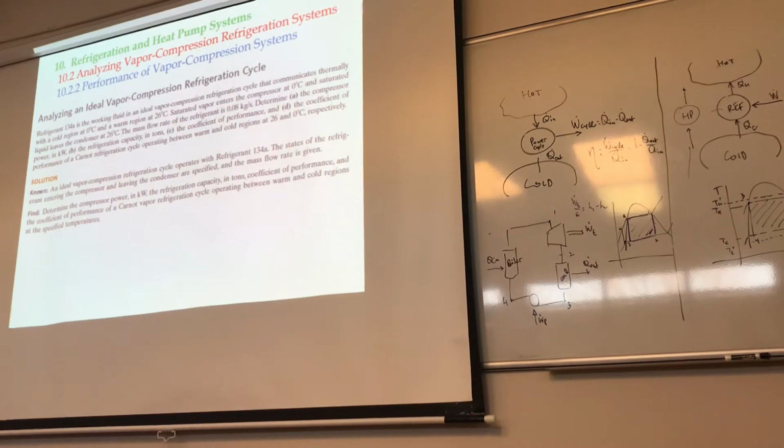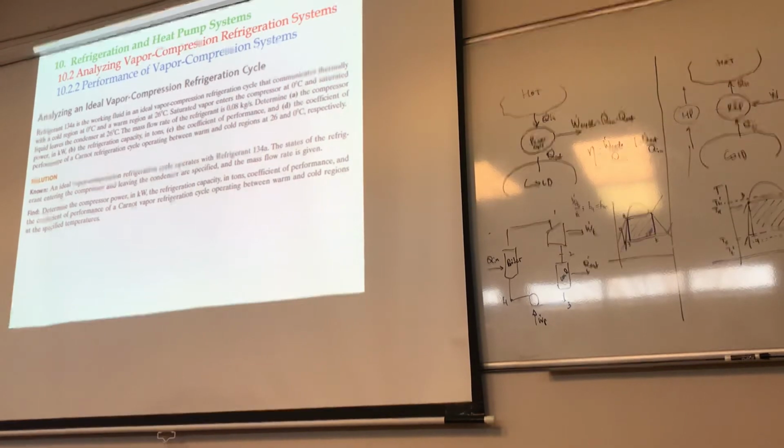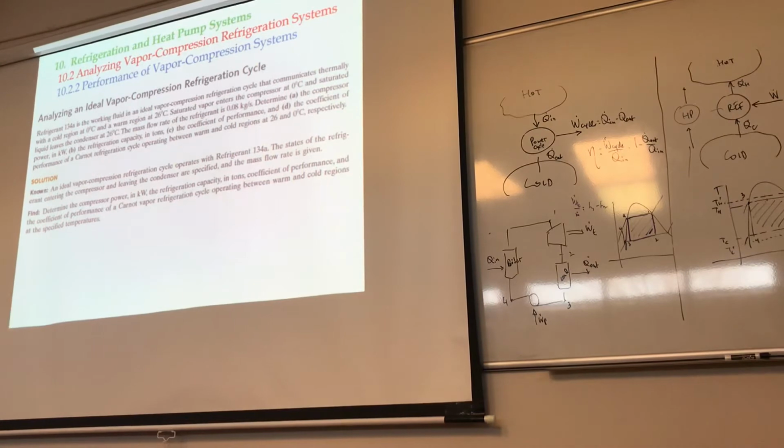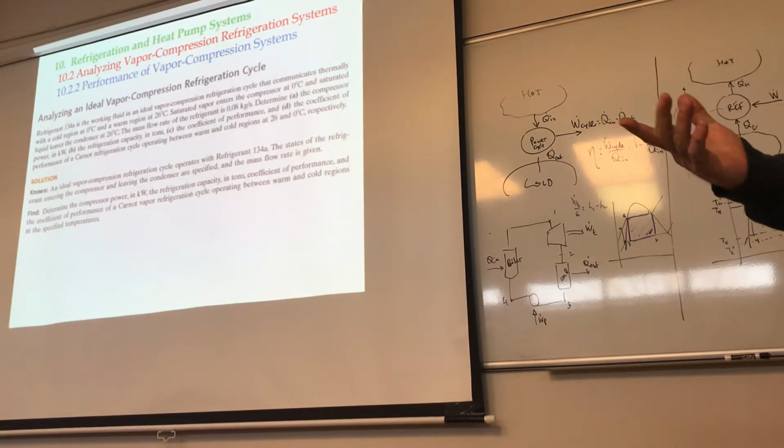Get to the table here. So 134A is A10, right? So at a temperature of, what did we say, 0? At state 1, the temperature is 0, yeah. 2.9. 2.9, yeah, so that's what the pressure is, okay? So what is H for state number 1? 247.23. Okay, that's pretty much it, okay?